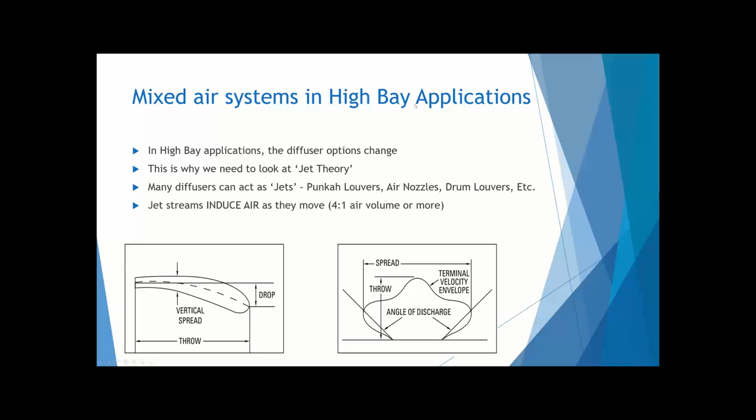So, mixed air systems in a high bay application. Let's apply that theory and bring it into a high bay application. You're no longer using a diffuser that is going to hug the ceiling, because there might not even be a single thing near the diffuser that you could hug. And not only that, but you would need a much longer throw to actually reach the floor like it did in the low bay system. So this is why we need to look at jet theory.